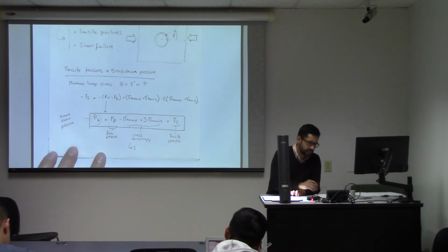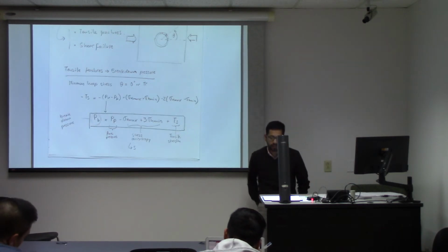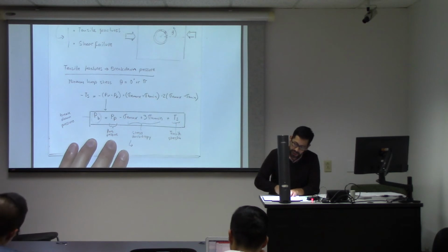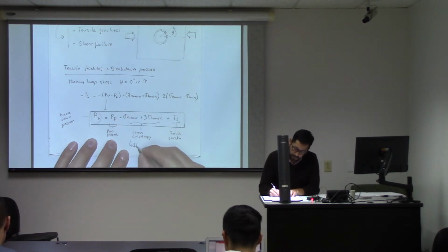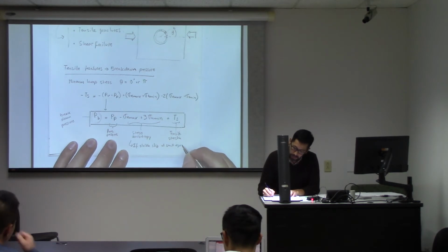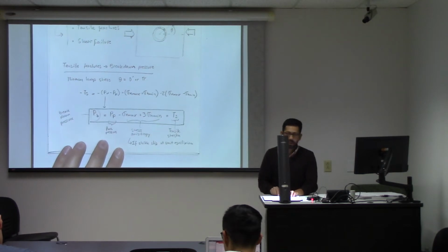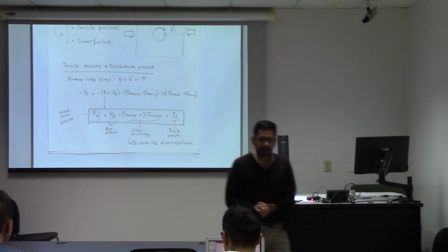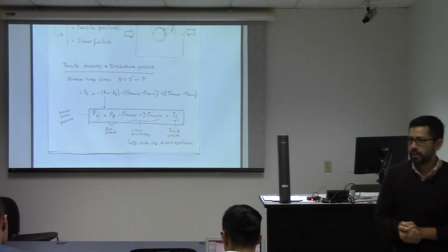if we have an example of a strike slip regime, and also you were to assume that the faults are at the limit of equilibrium, and we assume a friction angle equal to 30 degrees.